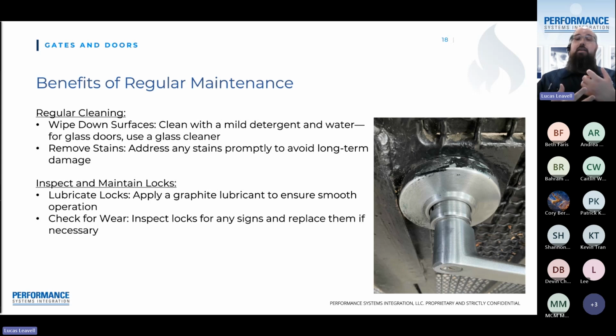Apart from that, then there are the lock sets, there are latches, there are moving components that people put their hands on. Those do need to be maintained as well. Within our division, we will maintain those by lubricating them. We will adjust them. There are little pins and screws on the inside we can adjust so that they're easier to turn. Or if they're starting to get loose, we can tighten them up a little bit. This regular maintenance ensures that your lock, which these are not cheap locks sometimes, especially for heavier gates, they can cost in the thousands of dollars, are being well cared for and will last a very long time.